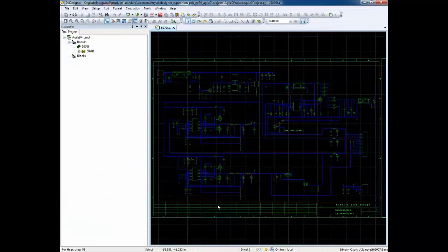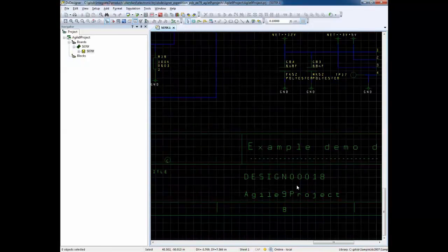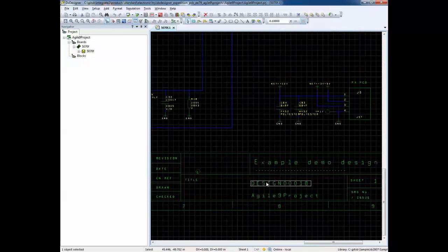After the save module has completed, we see that in our design project the metadata has been updated. The number of a design object is stored, and also the name of the design object is stored in the drawing frame properties. The set of metadata which is synchronized between PLM and your design project is configurable. For example, we can annotate here the PCB number and the number of the top assembly and so on.